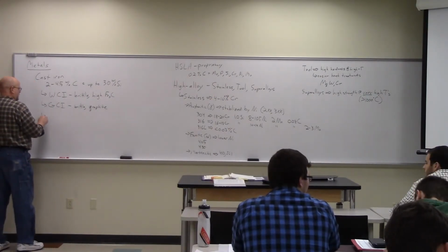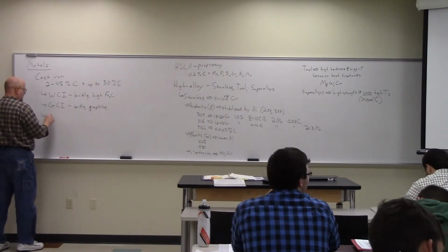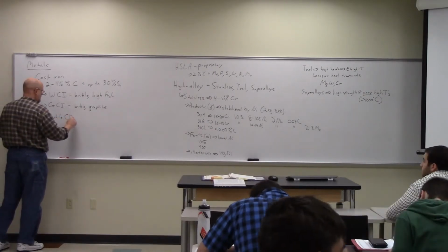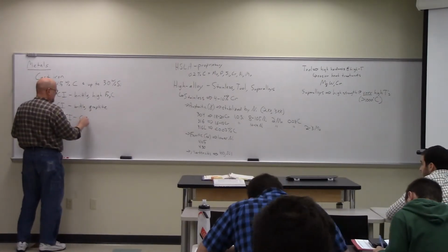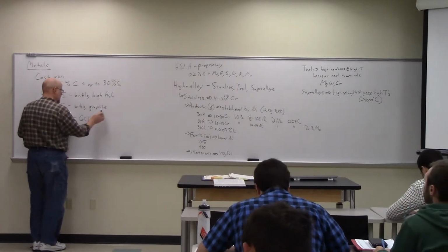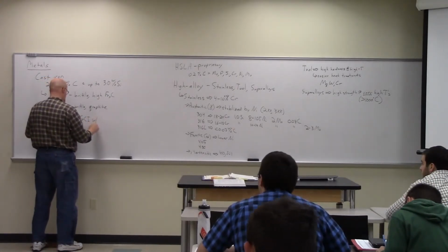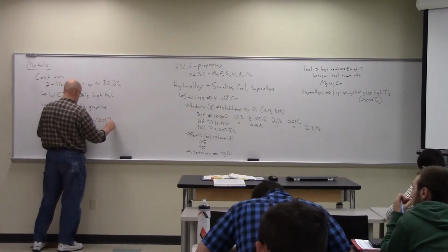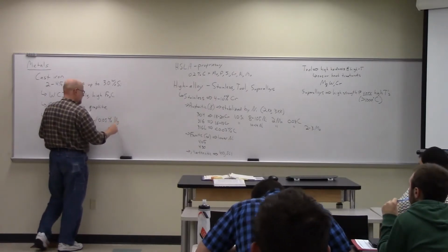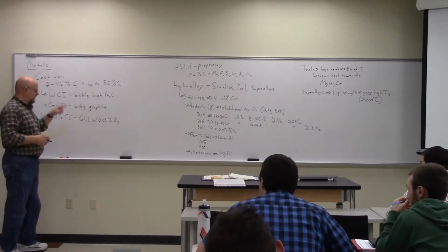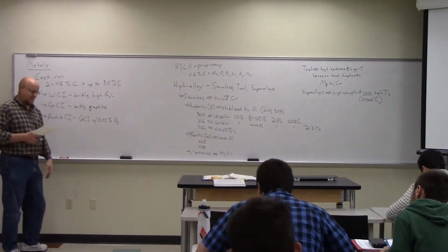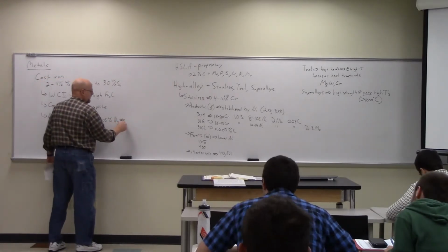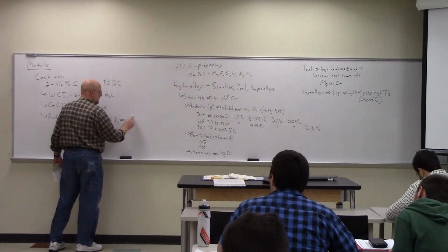And then the third category, or another category, is what's called ductile cast iron, which is basically just gray cast iron with 0.05 weight% magnesium. M is magnesium. Anyway, Mg. And so what this addition does is it makes the graphite spheroidal.